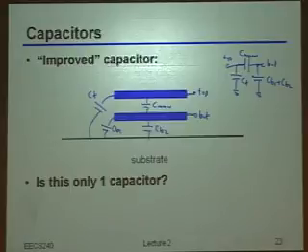Now, just to be clear, between CB and CT, meaning the parasitic from the bottom plate versus the parasitic from the top plate, in the particular example, which one of those two do you think is worse? Meaning higher. Bottom plate. Yeah, bottom plate, right? Because it's got not only just this fringe, it's actually also got that parallel plate. And even worse than that, it's closer to the substrate than the top plate actually is.